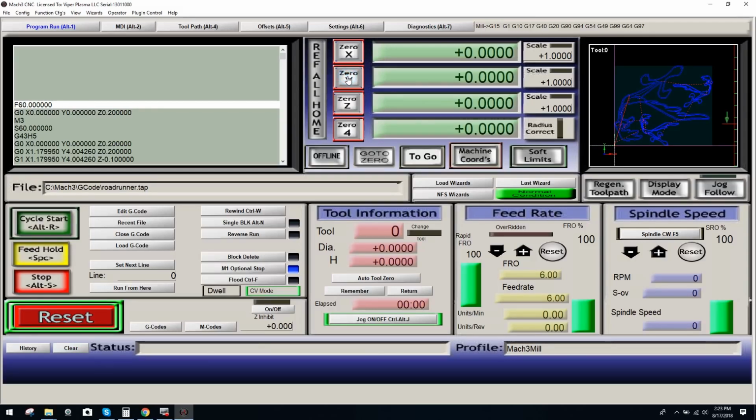You always want to zero it out on the negative travel because, again, that's where you're going to call your zero position. Okay. Now, that's arbitrary in the sense that you can set that anywhere you'd like as far as an offset. For G54 default, I recommend always setting it at a 0 point in a negative motion. However, it's your machine. If you decide you want to actually machine from G54, it's totally up to you. I like to leave G54 as a default.